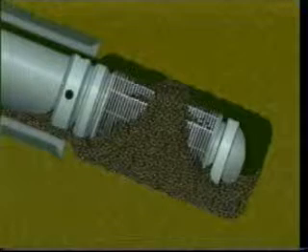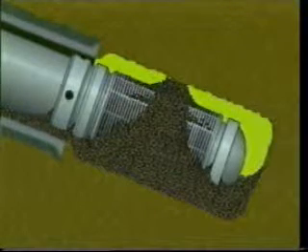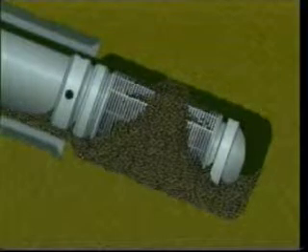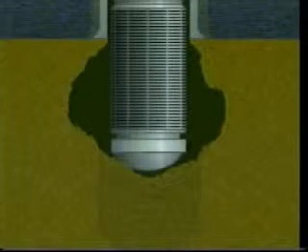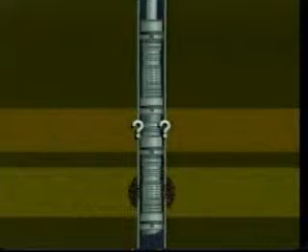Some mechanical problems associated with plain screens are incomplete packing on the high side of the hole in highly deviated wells, possibility of a formation slump before a gravel pack can be installed, such as in quicksands, or a limit to how close different screens can be run to each other, thus preventing independent gravel packing, such as in closely spaced intervals.